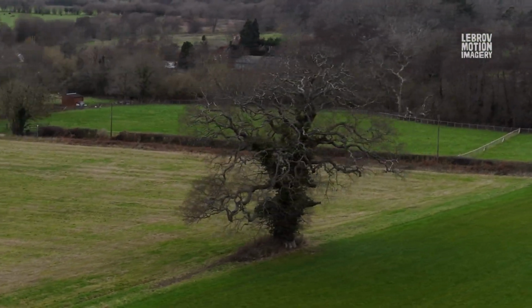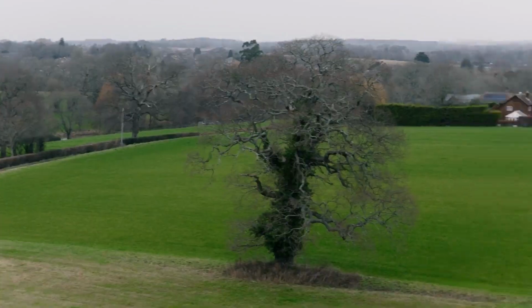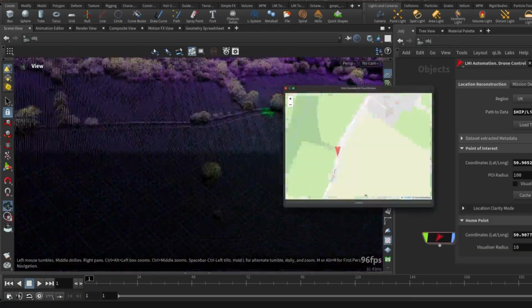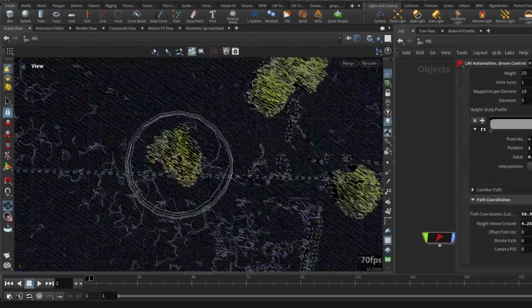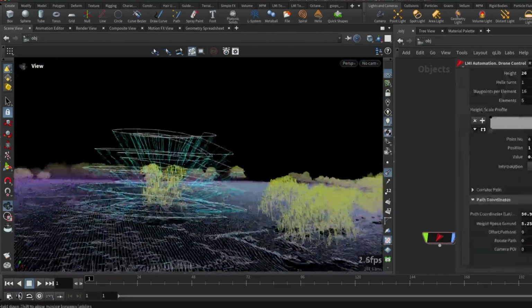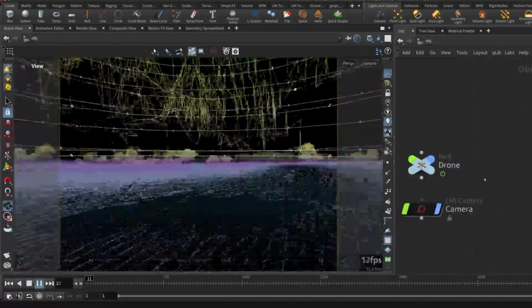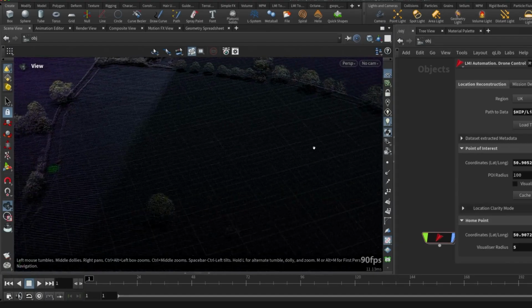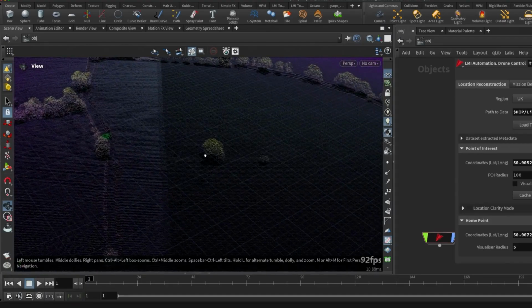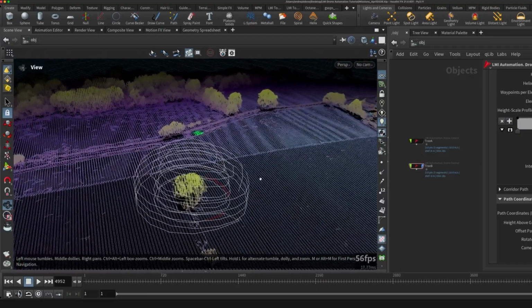So I started to experiment with drones by manually flying around the trees. If you know anything about Gaussian splats, they love continuity. And manual drone operation around the tree is choppy. So I went ahead and developed a Houdini tool that allowed me to pre-plan the flights and then automatically deploy them on location. What sets this approach apart from others is that I'm utilizing satellite LiDAR data, and I have full elevation of the trees and all the objects on the terrain, so I know exactly how high the tree is and where I need to fly to get the best coverage possible.